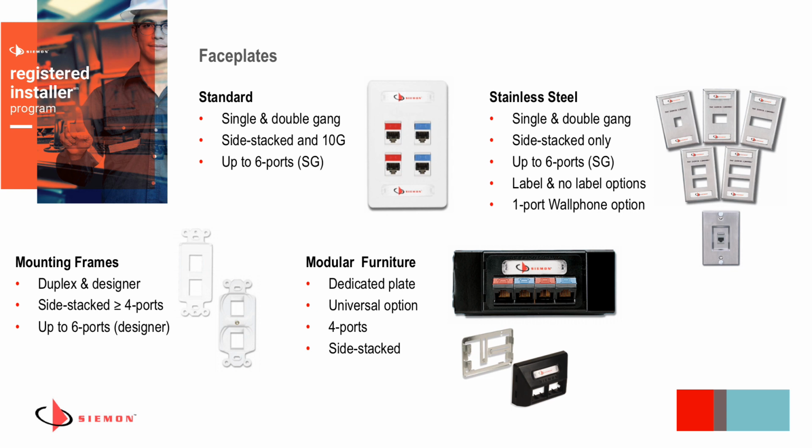In the bottom left, we show mounting frames, which are referred to as our duplex, which are more of an electrical style frame, and our designer faceplates, which are more of a Decora style frame. These are for customers who prefer to have their connectivity look and share a similar appearance to their electrical systems. So for side stacked outlets, you can put up to 4 ports. For 10G, you're really just talking 2 ports here. So something to keep in mind, there are some density limitations with those, and those are also specified on the duplex or electrical style versions of that. They're specified for whether they're for use with angled or flat modules.